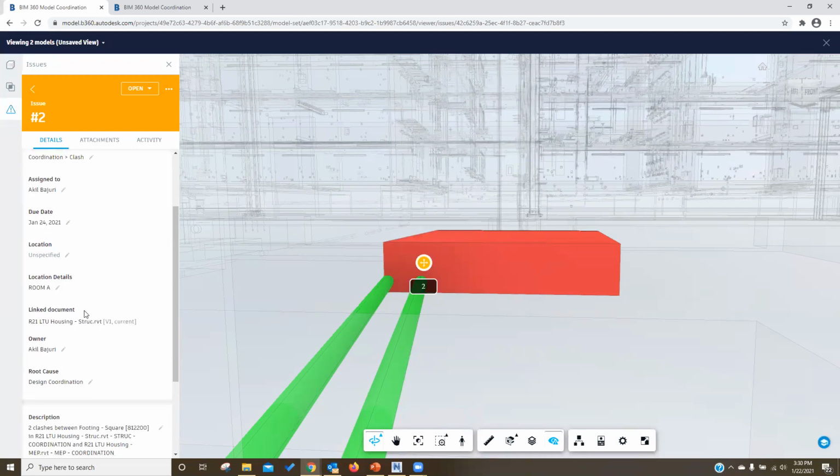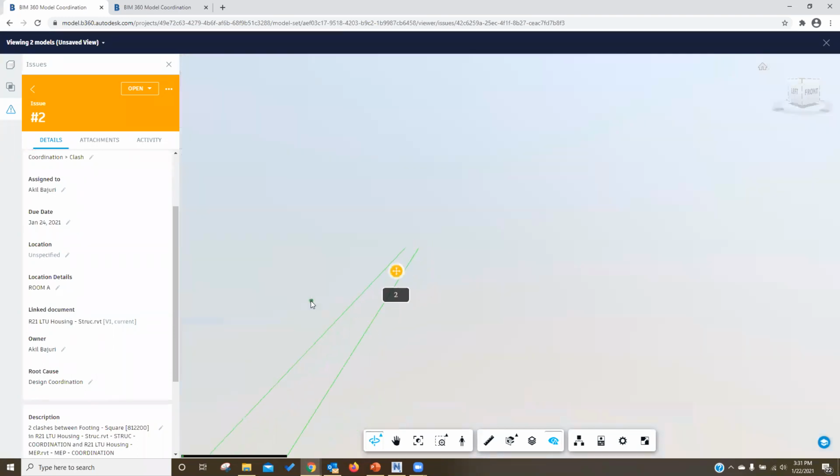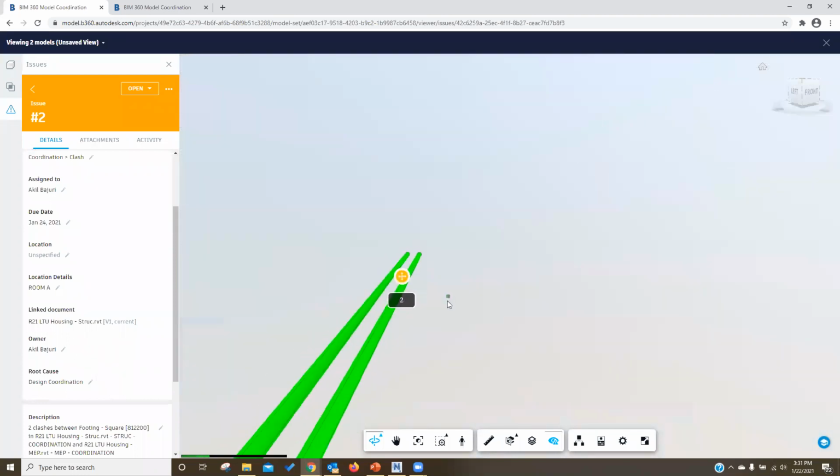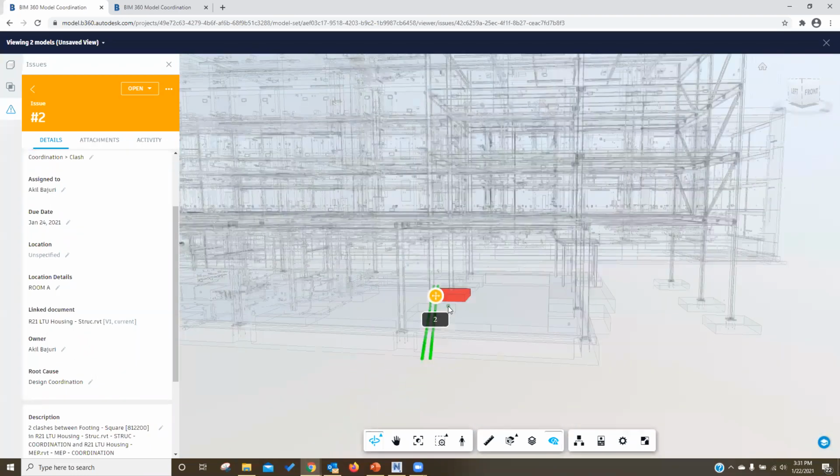And what you need to do next is, as a consultant, if you have to fix the model, you have to go back to the models, repair, and re-upload again in the same location and platform. And once you have done this, the next thing is that when they run the repaired model, it will be considered resolved. It shows you whatever clashes remain, but the resolved clashes will be stated as resolved. And this is how we use this cloud platform to speed up the process.